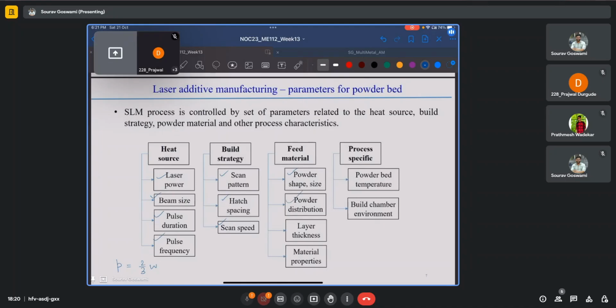Yeah, we discussed the distribution. The layer thickness which we choose will dictate the deposition times as well as the part quality. So if you opt for very thick layers, then we'll lose out on the part geometry. However, the production times might be lower, so it might be suited to simple geometries. However, if you opt for very thin layers, while we will be able to preserve the geometry of the part and our post-processing effort would be lessened, the time taken for the print would increase greatly.